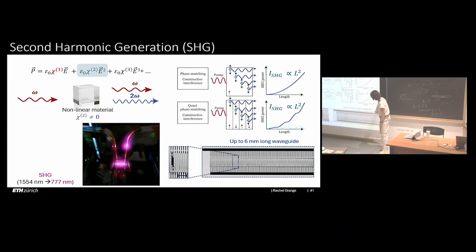Yeah, so what you see here, a very important tool for us is multiphoton microscopes. Even the ones that the biologists are using, we are heavy users of biologists' microscopes, so that we can really watch the second harmonic generation and see. So those are the electrodes, interdigitated electrodes, where you apply a very strong field, above the coercive field of your material.